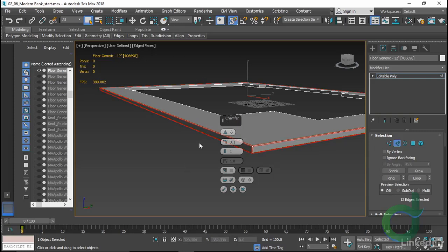We've got a lot of options in here. Are we chamfering by triangle or quad? How many segments do we have? Are we opening the chamfer? Are we smoothing it or not? And so on. I'll uncheck Smooth because I want this to be exactly faceted, as if it was made with 45-degree corner strips in the concrete form. Then I'll click the checkbox to OK the chamfer.